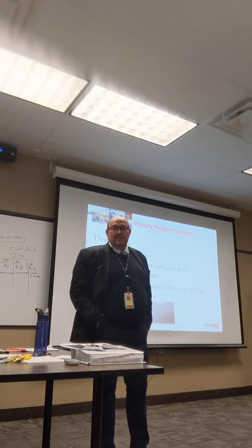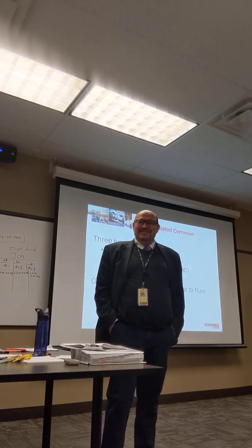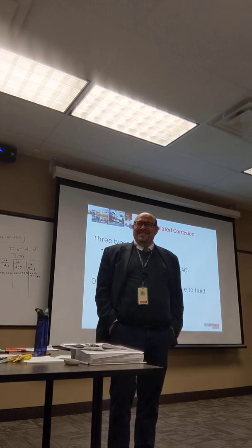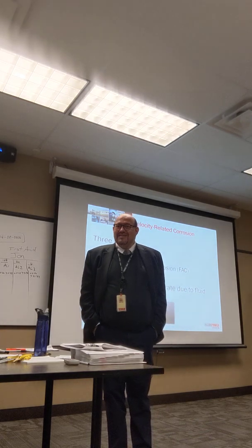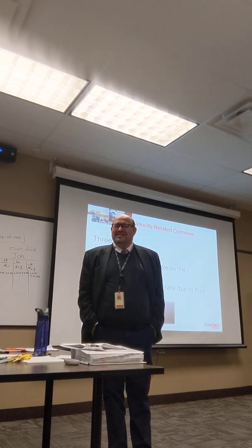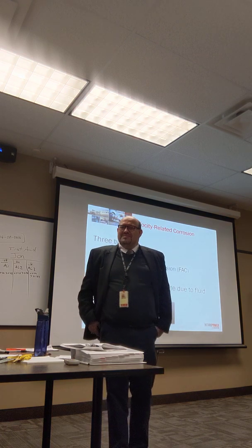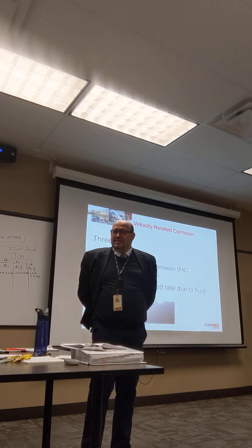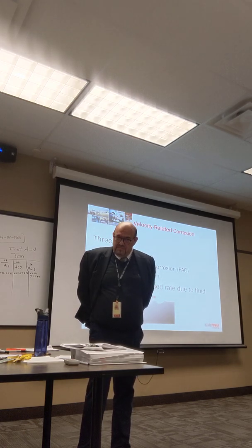In fact, in chemistry, we have changed pH many times to minimize dissolution of the magnetite coating. Because many times if your layer is getting dissolved at high temperature and different pH, along with the flow velocity, you will get some portion getting dissolved. So thinning will happen, right? Yes. So we have changed our pH values from time to time, as I mentioned earlier. In units 4 and 1 we have changed pH to minimize feeder pipe thinning, as well as to protect fuel bundles from getting the black coating.